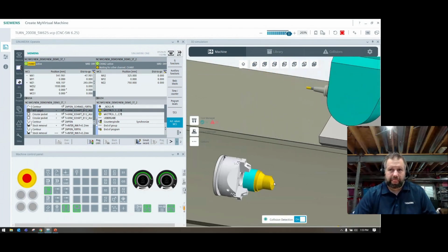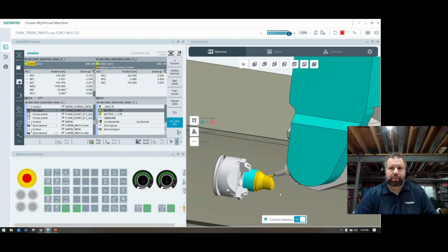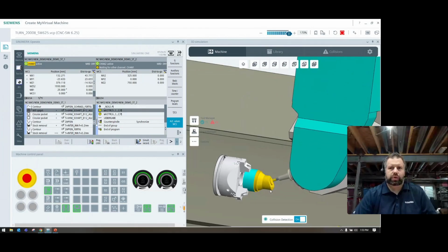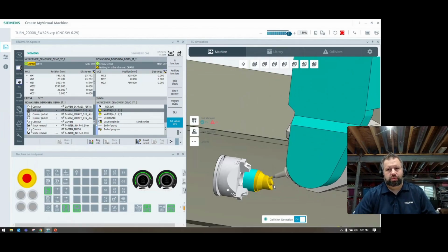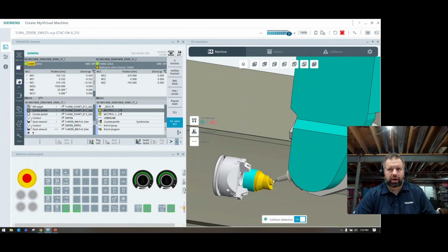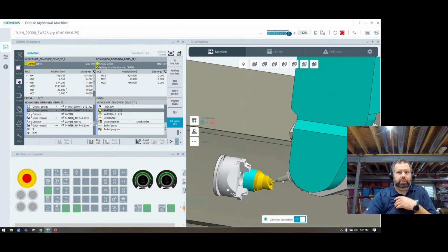We could do it with a boring tool, but now if we had a shape or a contour, in this case a little bellow here, you couldn't do that with a boring head. Sorry, boring head. And I don't know if I completely agree with doing contour milling, but you couldn't do any type of shape or contour like Chris was saying here.